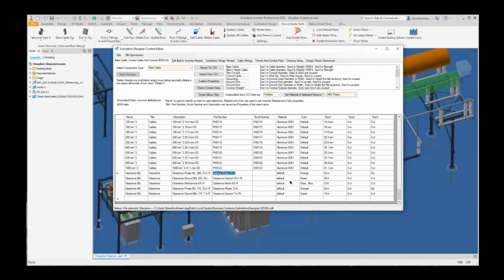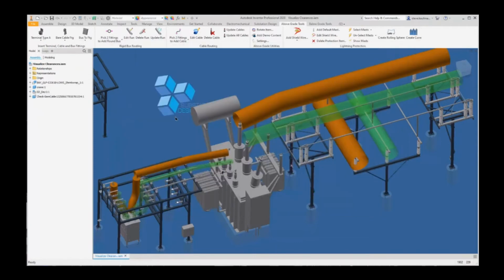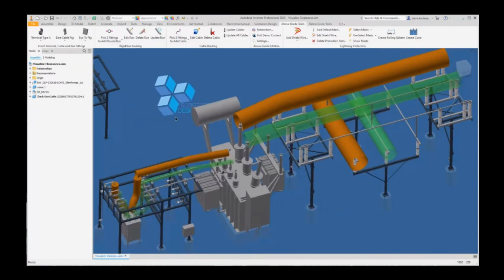The remaining material, of course, is just default. Doesn't matter what the material is. Key thing here is the orange, green, the blue. What we want to do is color it so we can see what it is and have meaningful colors to it. Any color you choose in here, you must have in your template model. Down over here, I put the size of the diameter. And of course, I put the units behind it. The units are important. You must have units here. And then, of course, the rest is default. So that's how we've selected and added that to the database.